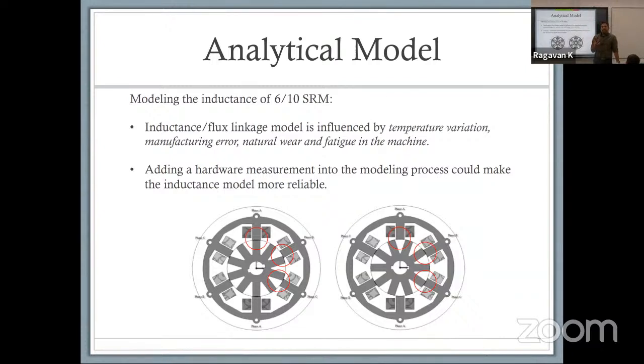We are by design simulating a 2D model, right? A 2D model, why? Because it's faster. You could do 3D, it just takes about 2 or 3 times the amount of time. The challenge with 2D is that you don't take into consideration the end turns. The end turns of your motor would have a substantial amount of coil that is turned around. You can put a percentage increase, but now you are guessing. It's an educated guess, but it's still a guess, right?